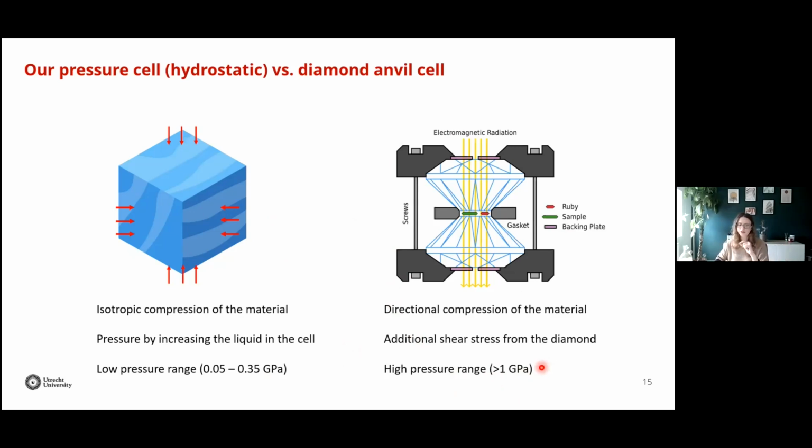So now you might wonder, okay, but what's the problem? Of course, if we want to have our device work, we cannot have a device that works under pressure. So we have to implement this pressure or strain through fabrication. And that's something that we can do for a low pressure range. We can have this type of pressure during fabrication, but we cannot have gigapascal pressure during fabrication. So for example, playing with substrate and thermal expansion coefficient can result in this type of strain, but not in this type of strain. So this is too high.